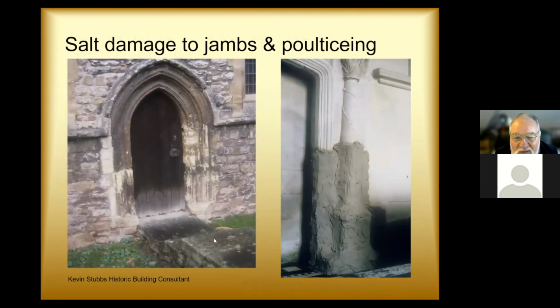So what can we do about the management of salts? Well, the first thing is to make sure that one reduces the moisture content at the bottom of the walls with adequate drainage. And we need to make sure that the drainage actually works and doesn't become a moat in winter. And then what do we do about the residual salts?